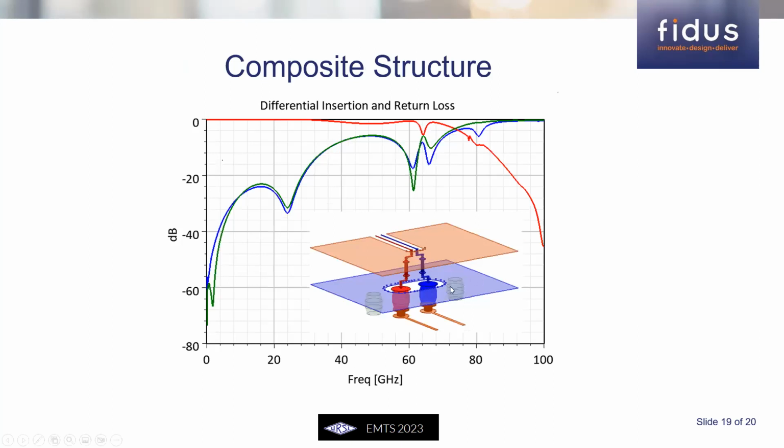So if I show you the result of a geometry that is optimized, we have used the piecewise optimization idea. Each one is optimized individually, and then we put them all together and optimize the entire structure as a whole. This way we keep the number of variables at a smaller value, and it limits the number of trials you need to do for a full 3D HFSS optimization. As you can see from the result, we could potentially get a desirable 20 dB return loss up to perhaps 30 gigahertz. Beyond that, it is largely taken over by the BGA ball pitch and the size of the BGA balls. Clearly, this represents a limitation in the best return loss that you can get in an integrated chip package structure that uses a 1 mm pitch BGA.